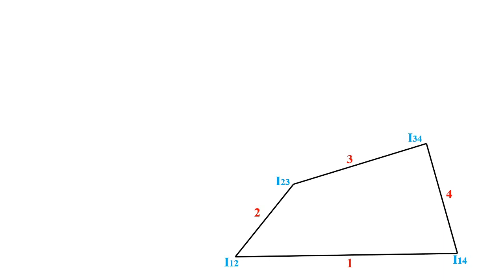Then what we can say is, we have I12 and I23. So where will I13 be? Just think I12, I23 and I13. These are the 3 centers corresponding to bodies 1, 2 and 3. Therefore, we have I12 here, I23 here. So where will I13 be? On the same line as these. Clear?